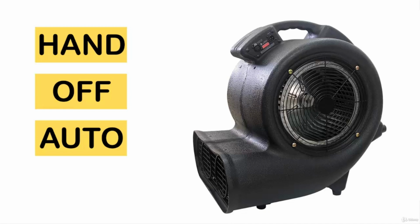Alright, we are ready to start putting some process logic into a ladder. We are going to start off small, so we are going to control this blower, and we are going to incorporate a concept called HOA control. HOA stands for Hand Off Auto, and this is a frequently used control scheme, particularly for digital, or I should say discrete devices. However, it's also used for analog devices, although it is a little bit more than just 3 buttons. For now, we're going to look at controlling a digital device in terms of hand, off, and auto.